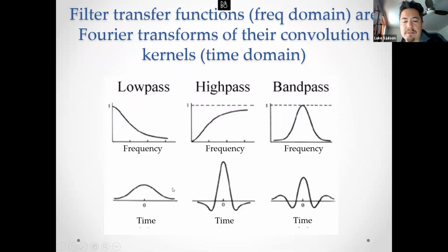So if you convolve some function of time with a Gaussian, say this is approximately Gaussian, with a Gaussian like that, then you get it blurred out. So to answer Elliot's question from before, what was the standard deviation in the image of the hot air balloon? It was the standard deviation in pixels of the two-dimensional Gaussian that they convolved that image with.